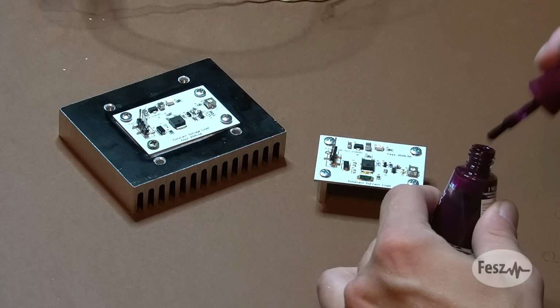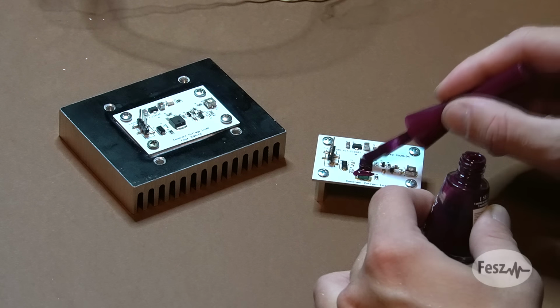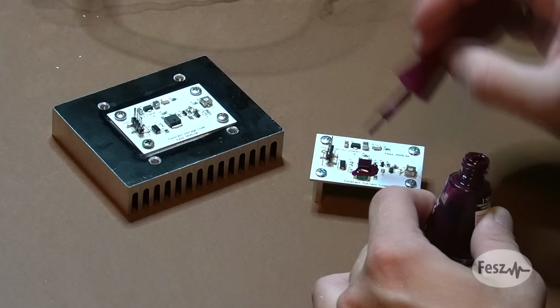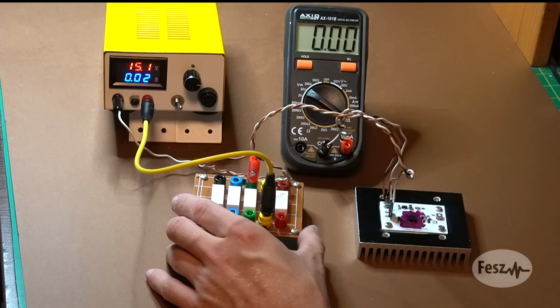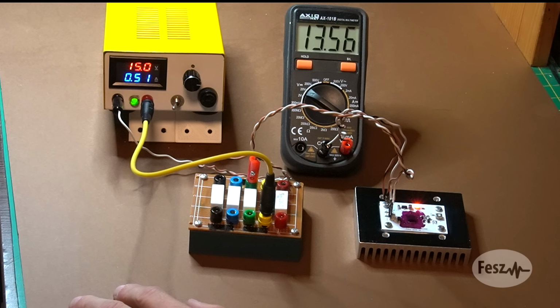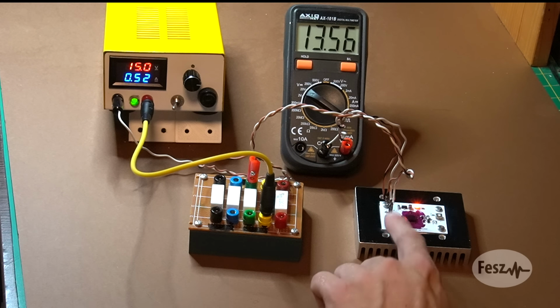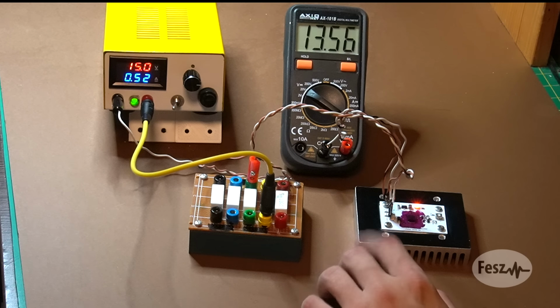However, the thing I was most curious about though was the thermal behavior. How well does an aluminum board actually transfer heat? So first, I applied some paint, which some might call nail polish, but I say it provides high emissivity and makes the transistor look fabulous. So first, to test the constant voltage load, I set it to dissipate around 6.8 watts. I let it run like this for a while, until the heatsink temperature stabilized, and then took some infrared pictures.